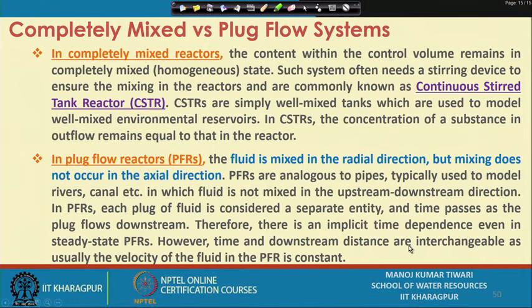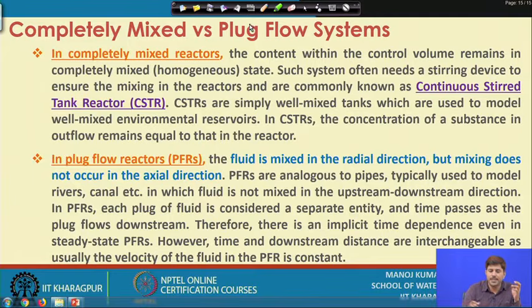The next specific case we discussed is completely mixed and plug flow system. So, what is a completely mixed system and what is a plug flow system? In a completely mixed system, as the name itself suggests, the content under the control volume remains in a completely mixed or homogeneous state. So, if there is a mixing of the content within the reactor, that we call a continuously mixed system. Such systems often need a stirring device, because how will you mix?